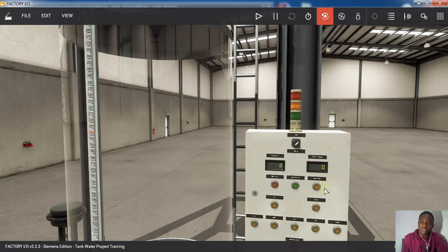And how did I differentiate this? I simply made use of the blinking function by enabling the internal clock memory in my PLC. When I enabled that clock bit, I assigned that clock bit to the e-stop. So when the e-stop is activated, the light will be blinking. If it is just stopped, there will be a solid light here.